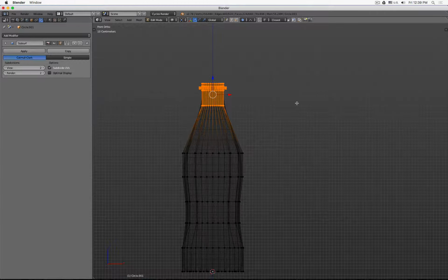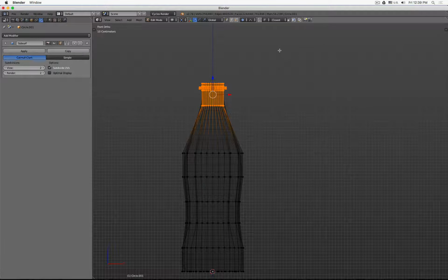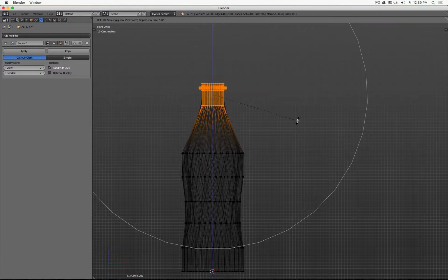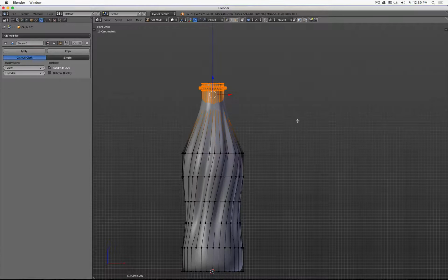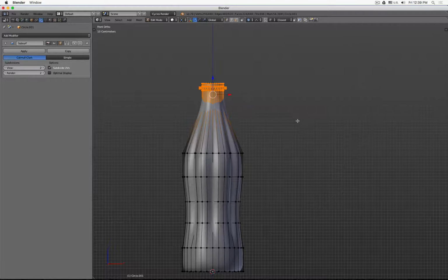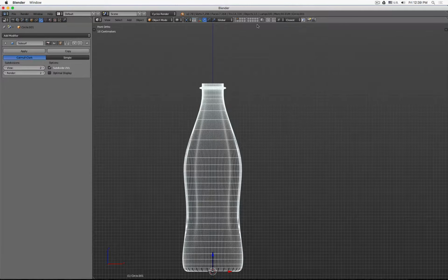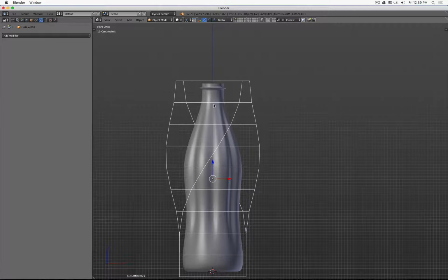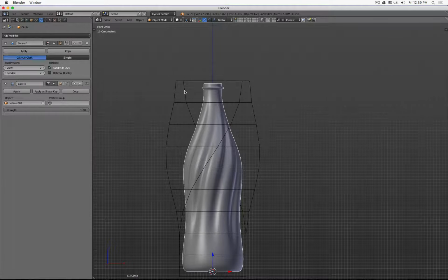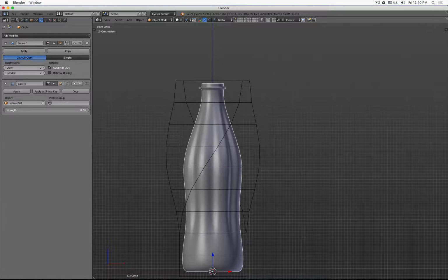For example, to undo this step, let's say we rotate this one with R Z by 50 degrees. This is something you would have to memorize, because with the same point selected, R Z minus 50, we can rotate it back. So it's nice and straight. So that's the upside and downside and the flexibility. And here, because this is all done nicely and interactively, you see I don't really have this problem.